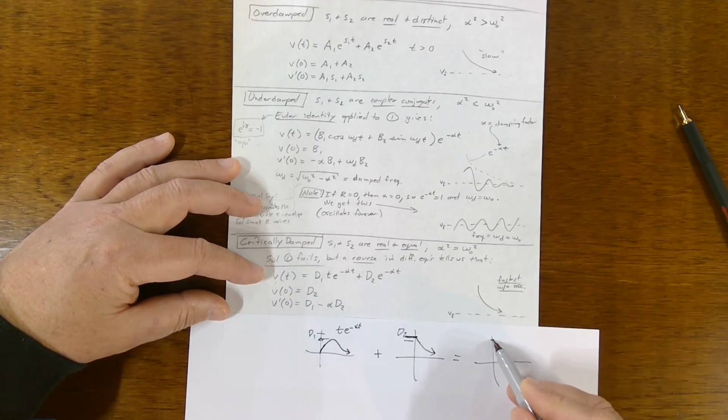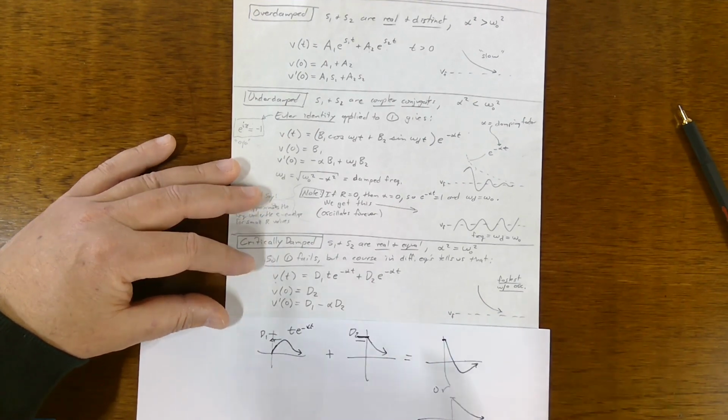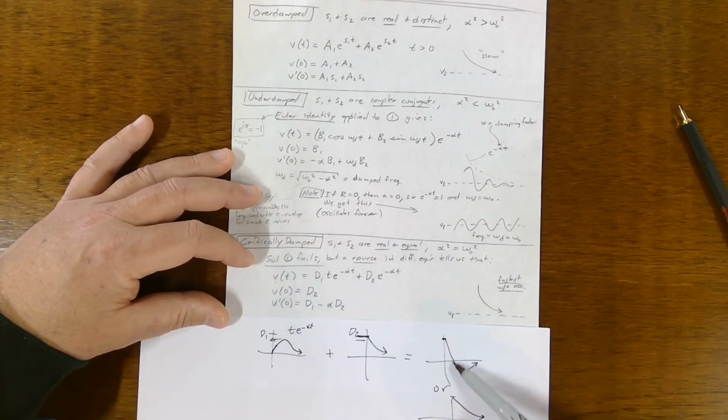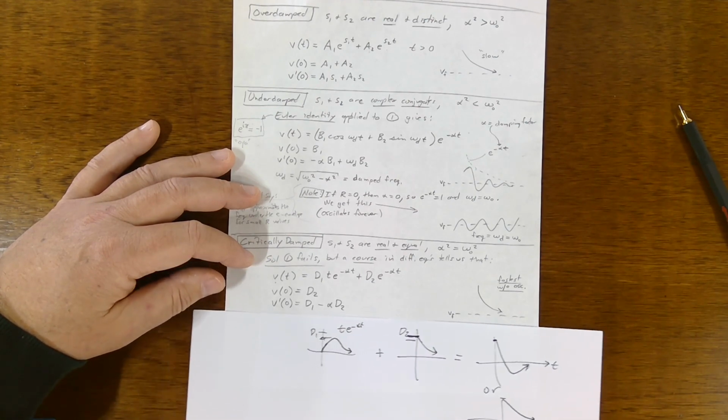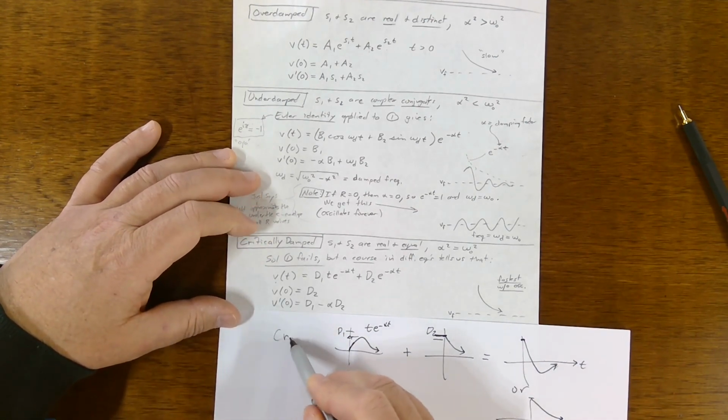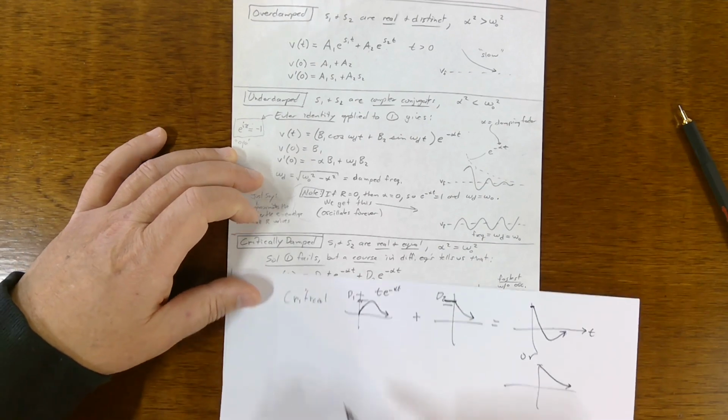Like, they're all going to start at d2, but they might go down like that, or they might go down like that. So what I'm saying is that a critically damped system can cross the time axis once. That's possible. Whereas the, so this is critical. Whereas the overdamped,